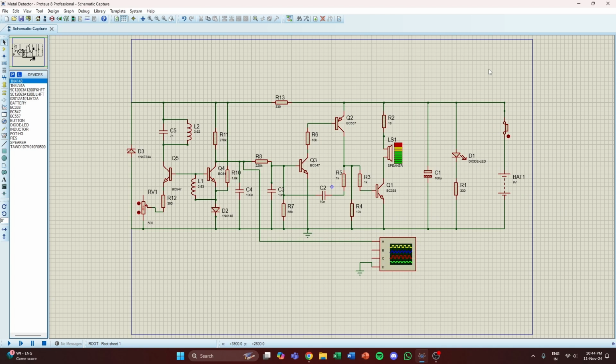This capacitor is discharged when the two transistors are turned off, and the second 10N is taken to the near 0 volt rail by the 1K resistor in series with another 1K resistor and the base of the driver transistor. It is fairly complex, and if you have a CRO, you will notice the waveform on the 10N capacitor go below the 0 volt rail. This is how the two transistor direct coupled amplifier turns into a variable frequency oscillator.